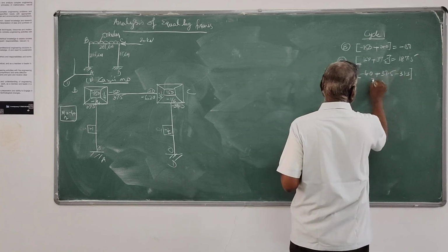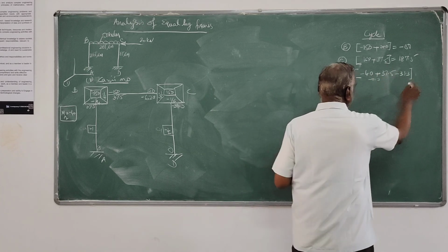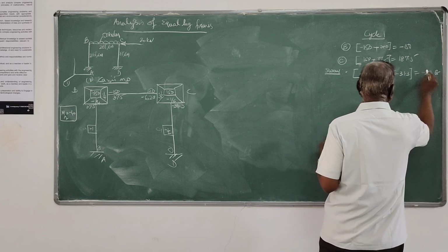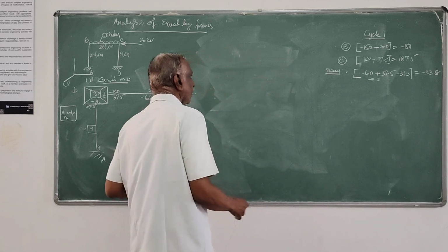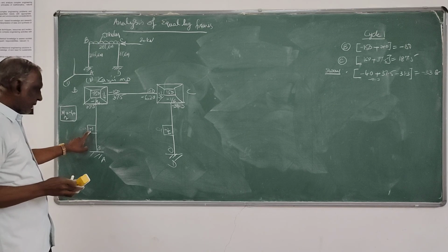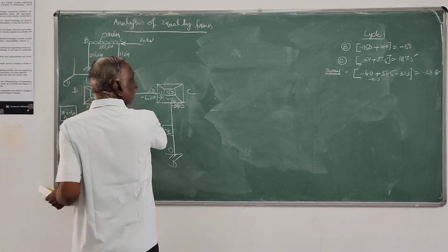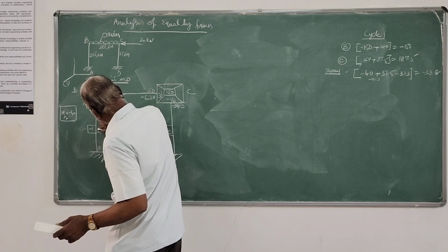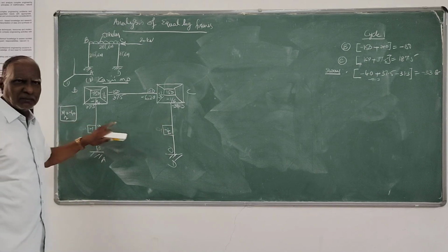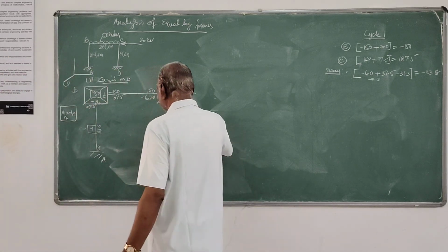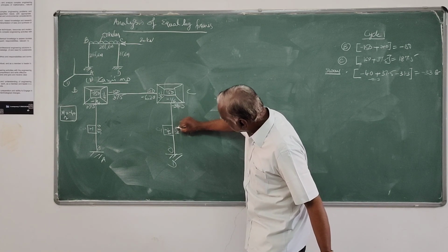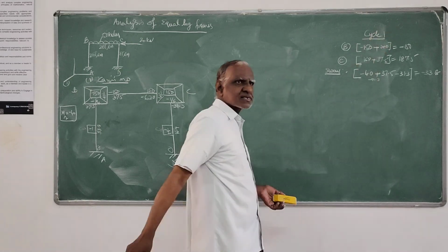So this is minus 71.3 plus 37.5, it comes to minus 33.8. That sum into minus 1, that is 33.8. I will write it in this fashion and write it the other way because it is column sway moment factors. So this is 33.8, and this is exactly half of that value, 16.9. So cycle 1 is over.